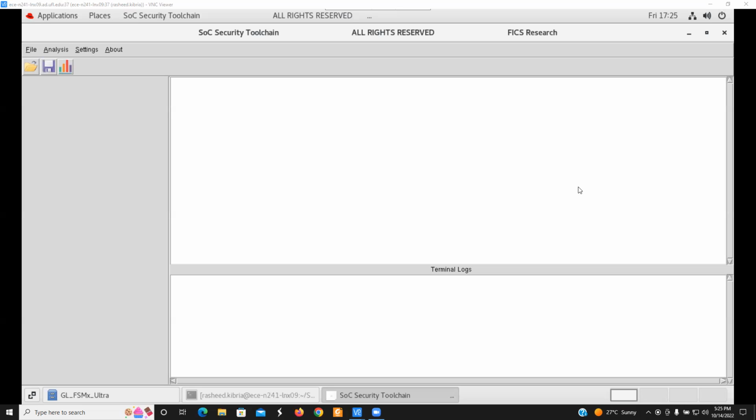One thing I need to mention: I have also modified the state encoding to binary, because the default FSM state encoding there was not that good. Most probably they wanted to use the one-hot encoding approach, but the state encoding was very bad. So I have changed that to a pure binary state encoding system. That means all the 46 states are enumerated from 0 to 45.